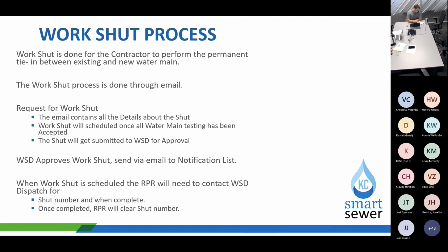Now, these requirements on here, I can't express this enough. Have your red line ready. Make sure you get that solid sleeve that they're going to be connecting with, that existing to another solid sleeve, because after they backfill, you can't get that type of information. This always happens during the work shut.